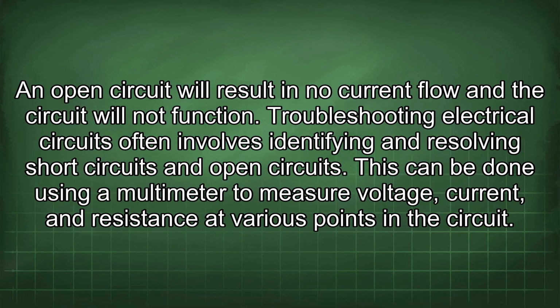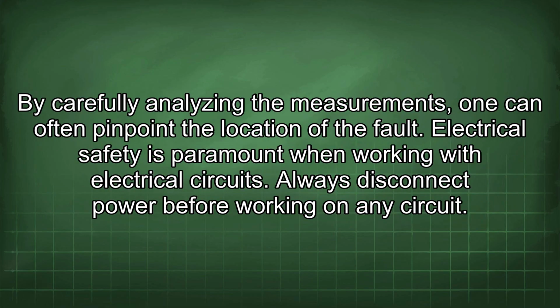Troubleshooting electrical circuits often involves identifying and resolving short circuits and open circuits. This can be done using a multimeter to measure voltage, current, and resistance at various points in the circuit. By carefully analyzing the measurements, one can often pinpoint the location of the fault.